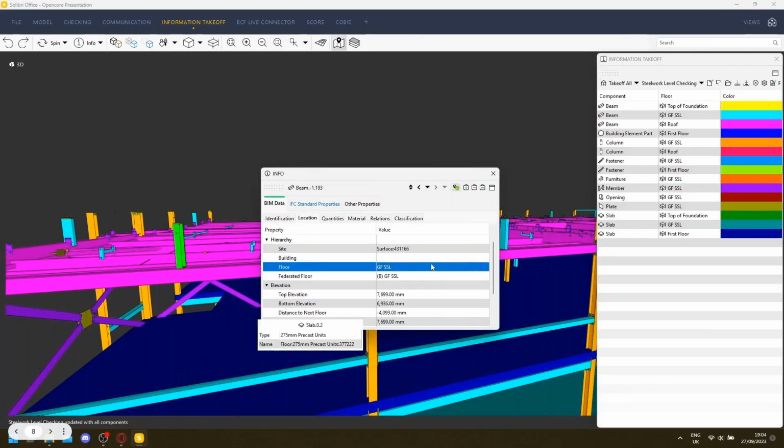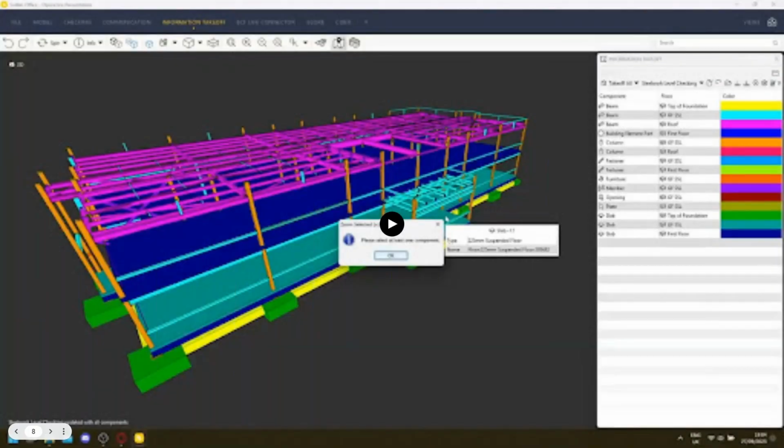Now that's quite a heavy-handed example. I didn't have the original model there, so what you're seeing is something I've knocked together. But even recently, that's something that I've seen in the past. Again, it's probably because model authors are working against the clock. They may think, I've got to get this model out. I will just take the existing ground floor steelwork and boost it up to the first floor, and that'll save me some time. They may forget to reassign it to the story.